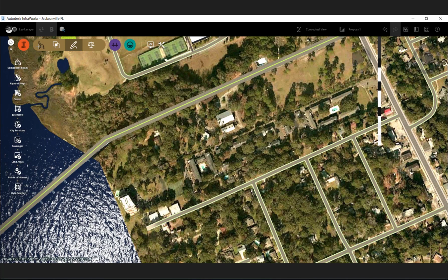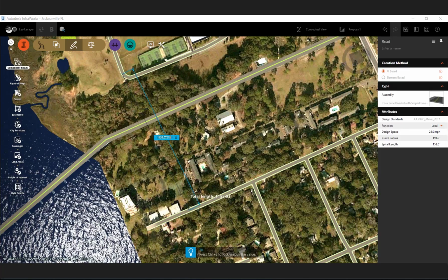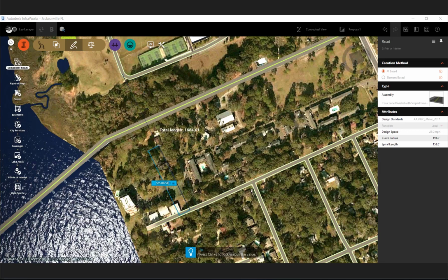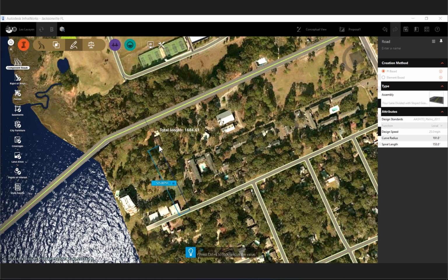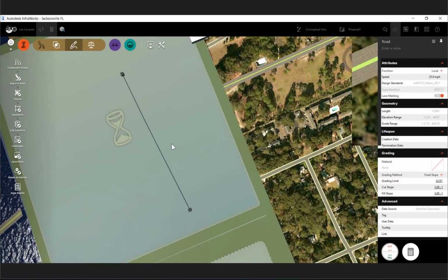And as that finishes, tying into those existing roads is not going to give me something really intelligent, not an intersection per se, but if two intelligent roads happen to intersect, I will get what is referred to as an intersection. And as that finishes it off, oh, come on, hit enter. I do have the possibility of having the software clean itself up nicely, but what I would like to do is talk about the intersection that actually gets created for me when two intelligent design roads cross, where I can choose a type of intersection, or as the software calls it, a junction.